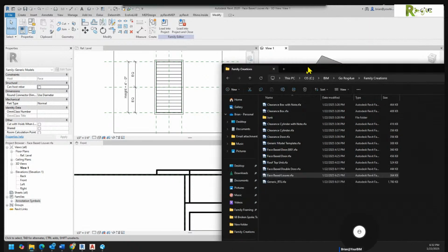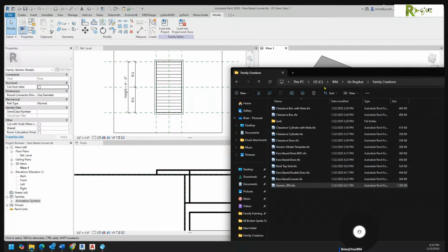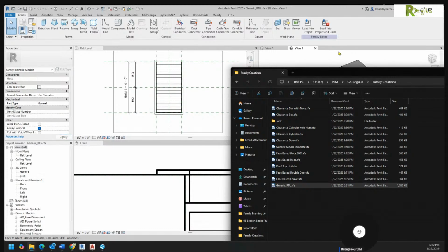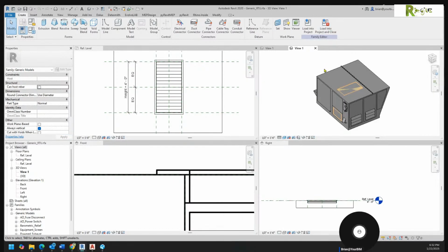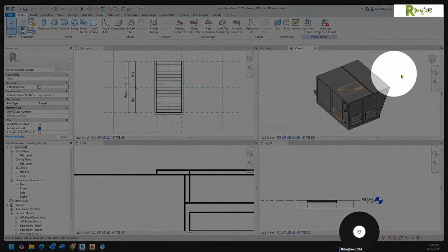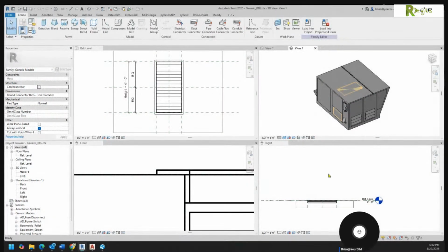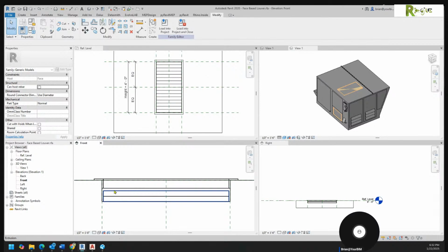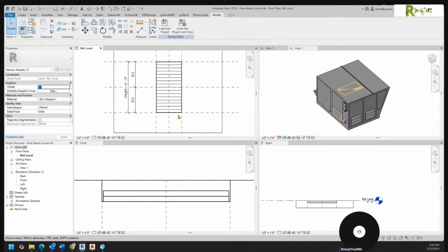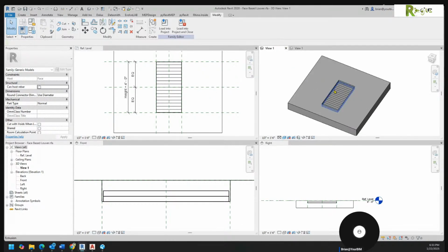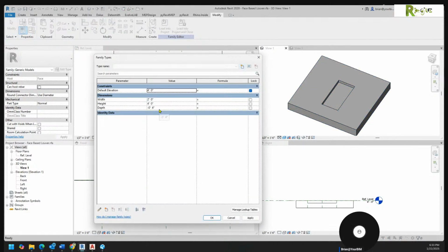So notice that I clicked in that 3D view, and then what I'm going to do is drag this generic RTU. See, I wanted it to open just like it did. I wanted it to open in this view right here, okay? See, that way my other 4 views are all good. So what don't I need? We're about to build that louver. So it does not need the frame. It's probably also does not need this box, right? But I do think having the cutting ability would be beneficial. And see, that's where the depth becomes real nice.